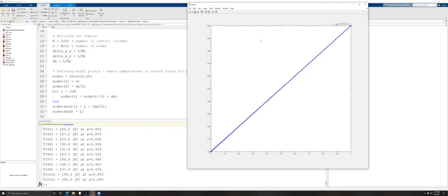Because in real life, you're never going to have uniform mesh density or uniform mesh spacing. There's always going to be curvature. There's always going to be weird things going on with your model. And for us to extend this in the finite volume method by simply predefining our nodal locations and our delta x east and delta x west variables, it runs very, very smoothly. Our solution algorithm doesn't change.